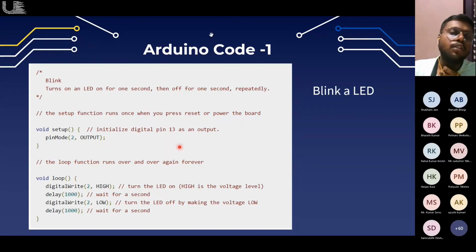The serial output can also be used as input to other modules like a GSM module. The TX1 RX1 pins can be used with the GSM module. The signals generated by the GSM module, such as coordinates, are mostly in the form of serial output. So that output pin can be connected to this input pin RX1. Then the Arduino board will receive the value of the coordinates.